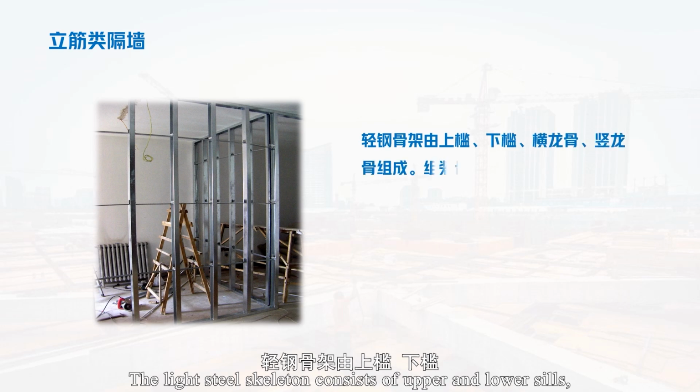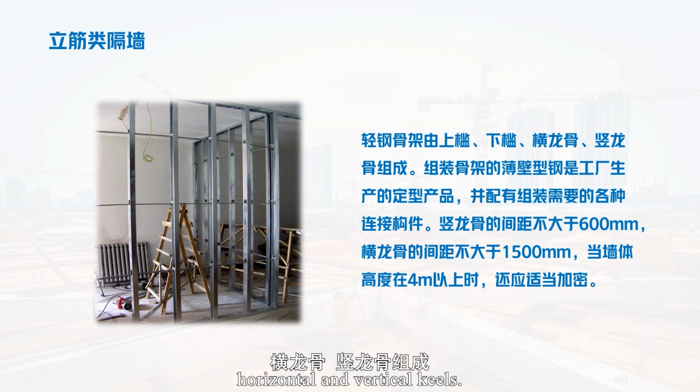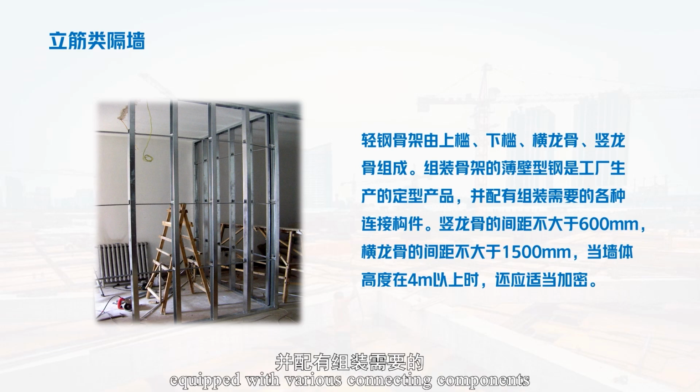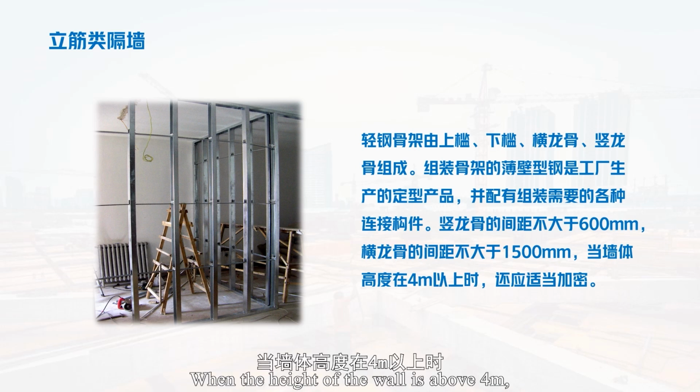The light steel skeleton consists of upper and lower sills, horizontal and vertical keels. The thin-walled steel for assembling the skeleton is a standardized product produced by the factory, equipped with various connecting components required for assembly. The spacing between vertical keels should not exceed 600 mm, and the spacing between horizontal keels should not exceed 1,500 mm. When the height of the wall is above 4 m, it should also be appropriately increased.